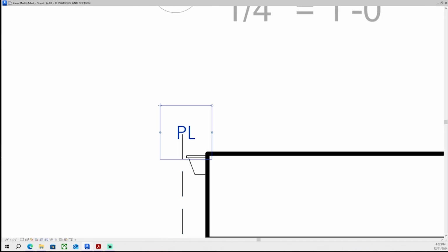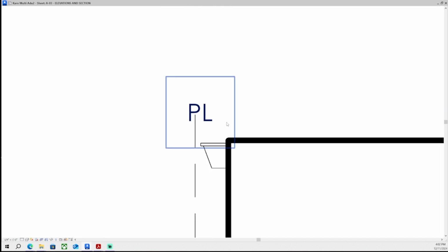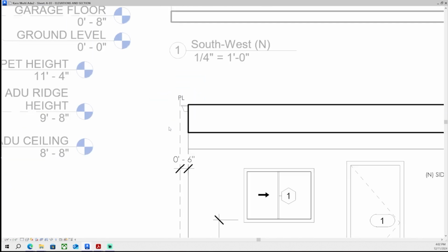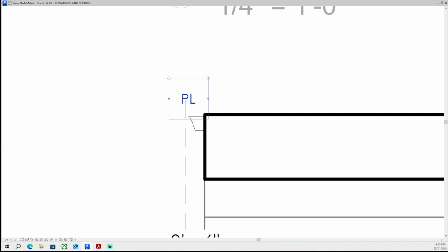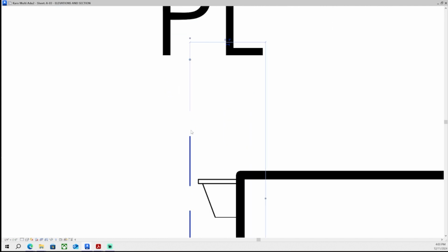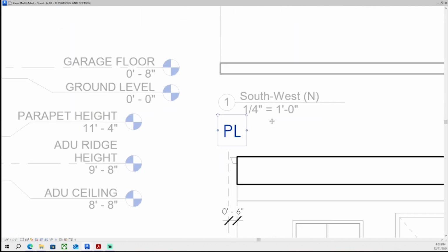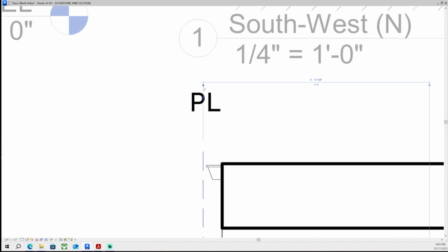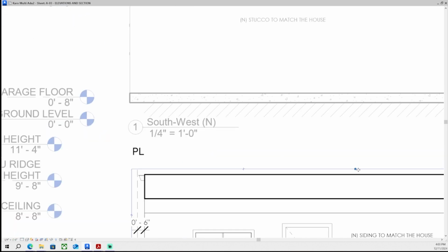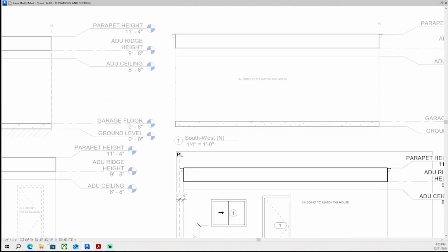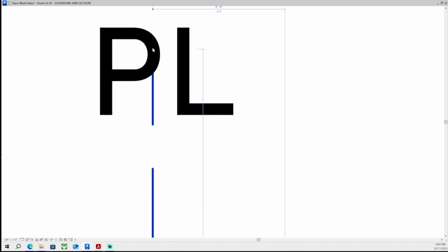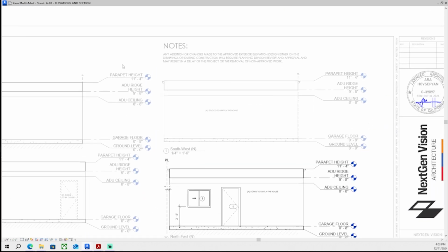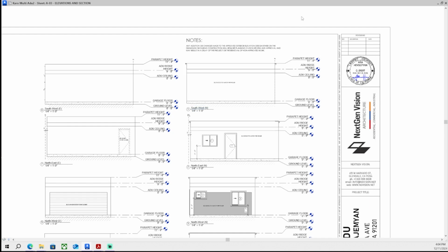So they also want to see the property lines on the elevations, especially when you're close to the edges, because this existing garage had pretty much a zero setback on some sides. I mean, here it was like 6 inches away. So on our elevations also, we show the property lines sometimes. Obviously, on the site plan, you see how the building is arranged on the lot. But on the elevations, where you're looking at the building from basically eye level, how a human being is going to see it, seeing the property lines there is also helpful.